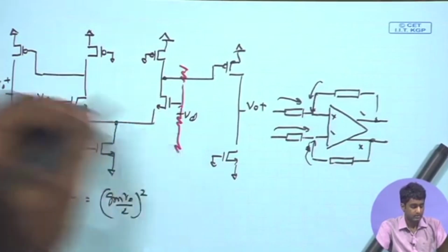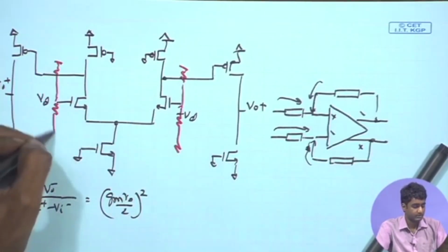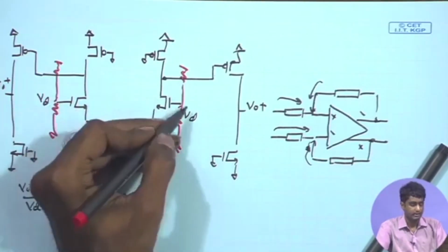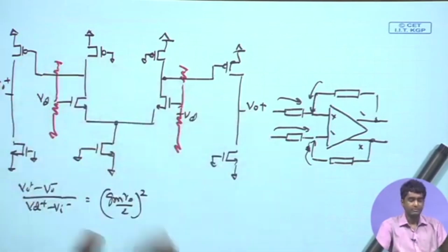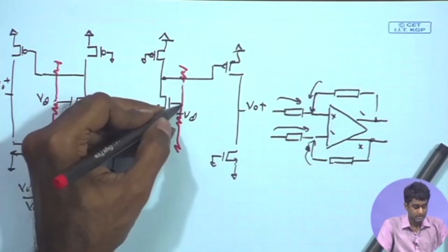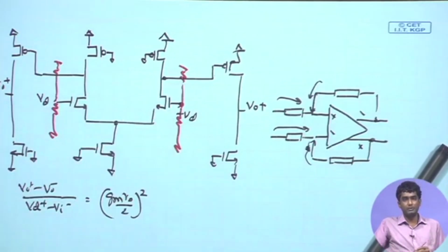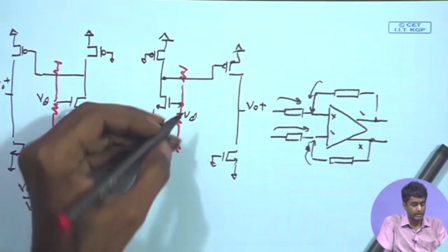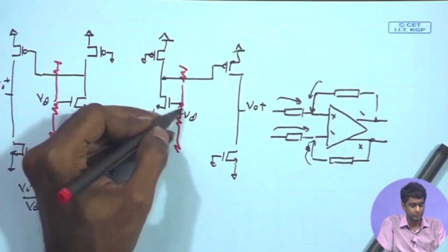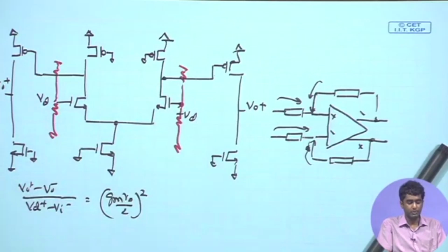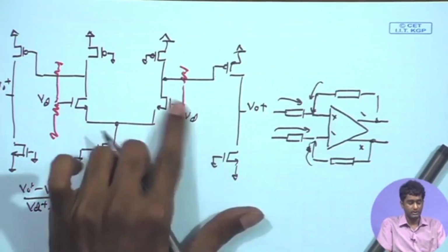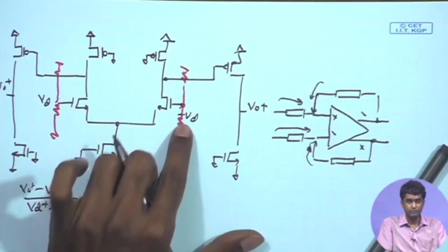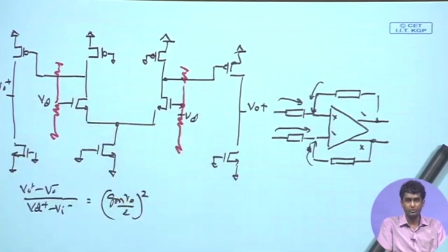You can connect a voltage divider to get an appropriate DC bias point that you want over here, and then you can use the capacitive feedback as we have discussed in the beginning. But once again, what is the problem with such bias? The biggest problem will be the noise contributed by these resistors, because ultimately these resistors are going to give you an input referred noise, which is going to come directly at the input port, and it is going to interfere with your amplifier's operation, and therefore direct resistive biasing may not be a good option.